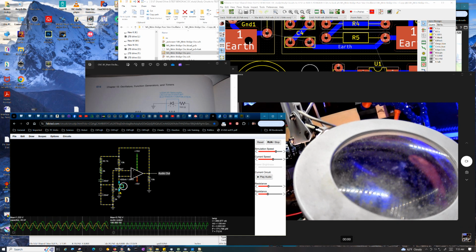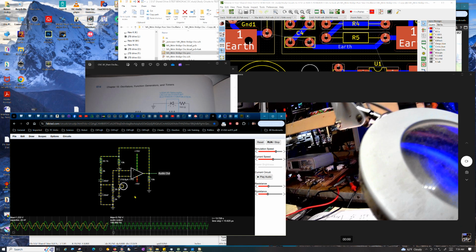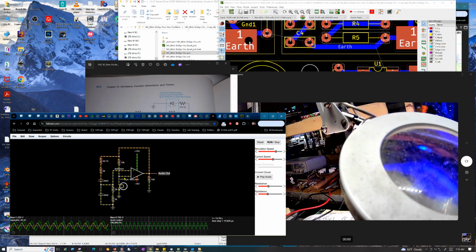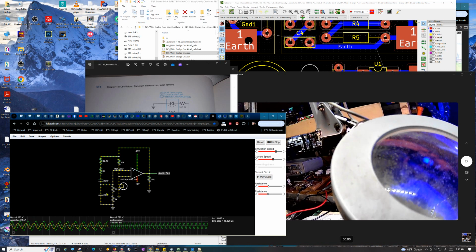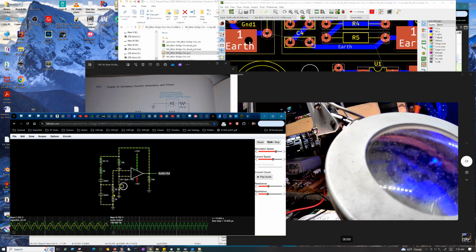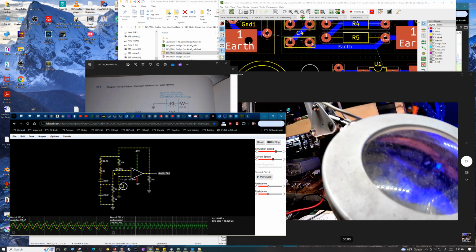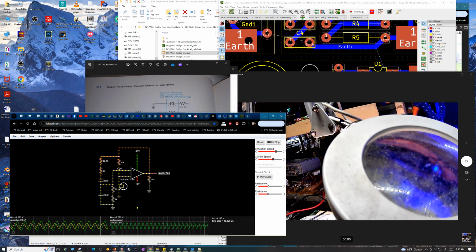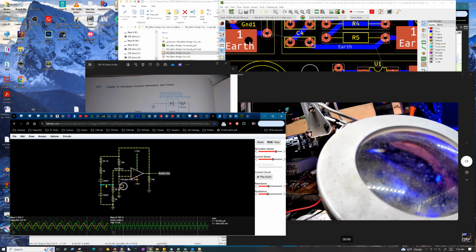Eventually the voltage gets too low and the thing kind of shuts down. That's its reference voltage, and it's trying to compare this, I guess, to the average voltage between these two impedances. This is a parallel impedance and this is a series impedance. They're going to form a voltage divider together, and that sweet spot is what creates the oscillation, I believe.